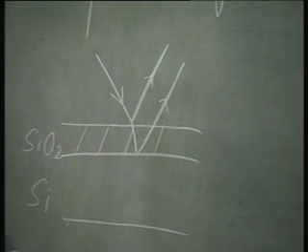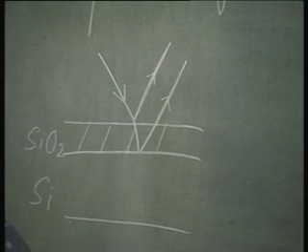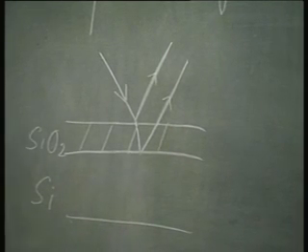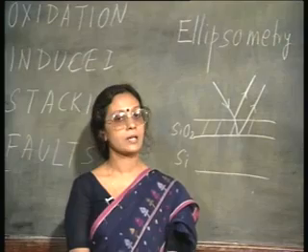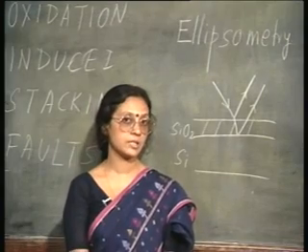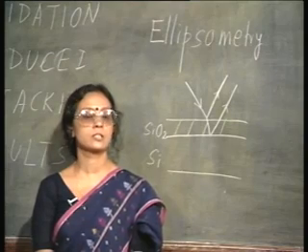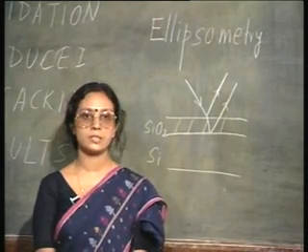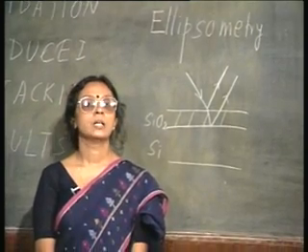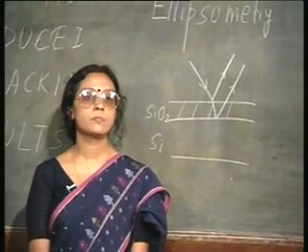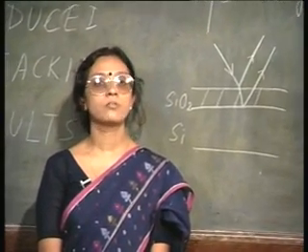So, knowing the refractive index, one can find out the thickness of the oxide film, and this is accurate within a few angstroms. That is a very large degree of accuracy. Within 5 angstrom or 10 angstroms, one can determine what the oxide thickness is. But even here, the path difference will repeat every 2500 angstrom.